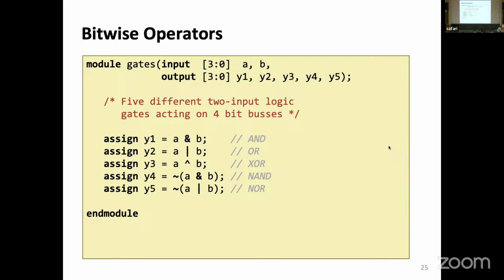Wires are not nodes. Wires are interconnections, so they are edges if you want, not nodes. But there's no limit on how many inputs there are. For outputs, it doesn't make sense to have more than one, although you can have many outputs if they are all tri-state drivers, and then things would work.